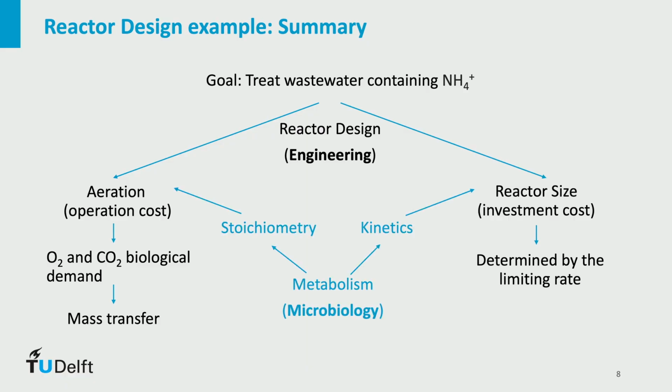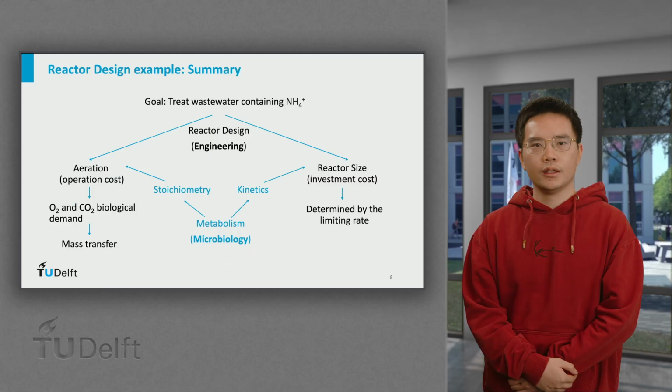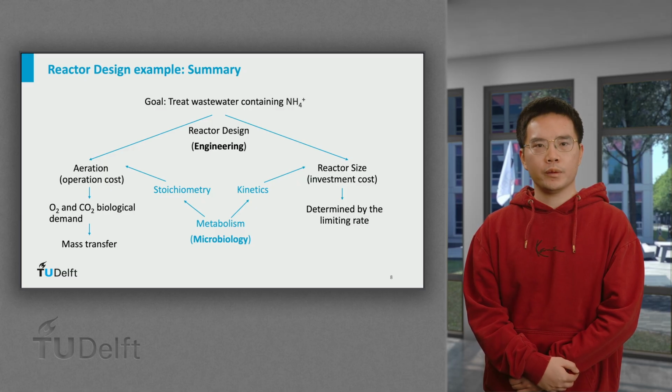If we step back, we can see how engineering design is deeply connected to microbiology. Aeration requirements is linked to stoichiometry. Reactor size is linked to kinetics, and both stoichiometry and kinetics are linked to metabolism, which is what we learn from microbiology.